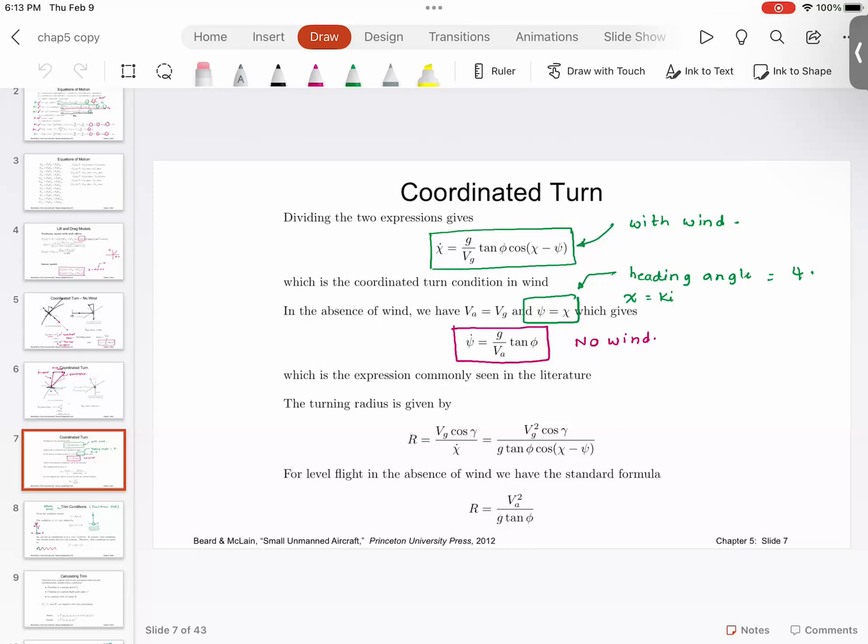So what you need to do is, at that time you need to decouple, and then you have to use some algorithms, like look at the coupling and then approximate it, and then just rely on the gyro data. Just don't use the accelerometer and so on. So remember this: if you get into flight control, whenever you are banking, you cannot trust the instrumentation, the IMU, or accelerometers and gyros.